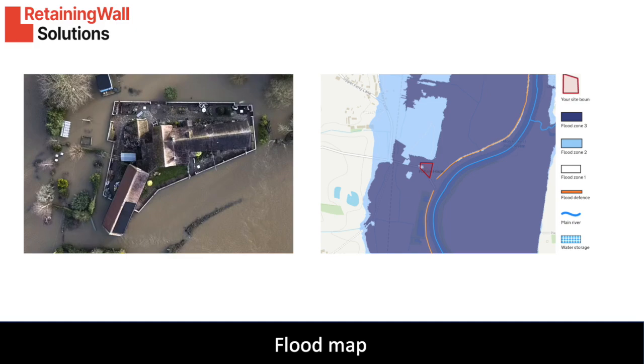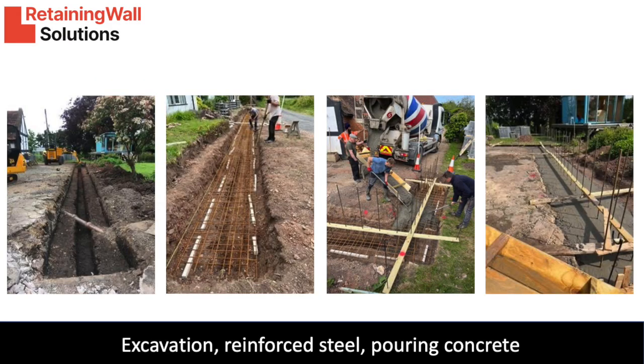The ground condition at Pixham House was gravel and sand. This means water will seep under the foundation and a pump sump is required to pump the water over the wall. A drainage system is designed with the wall for this purpose.